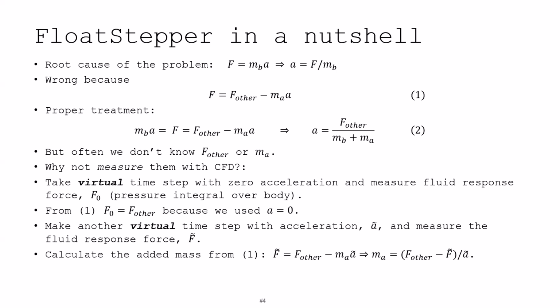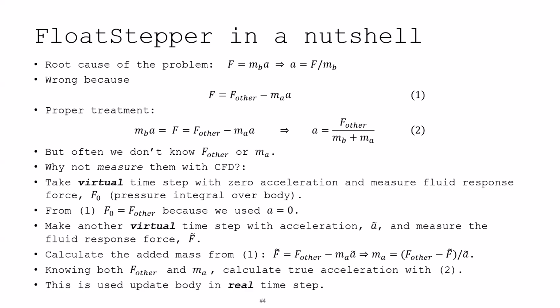proper acceleration. And then now it's just a matter of plugging these two into our acceleration expression, integrating that in time to get velocity and position of the body, and using that to get the boundary conditions of our fluid, for instance, pressure and velocity calculation. And then that is taking our real time step with a real added mass.